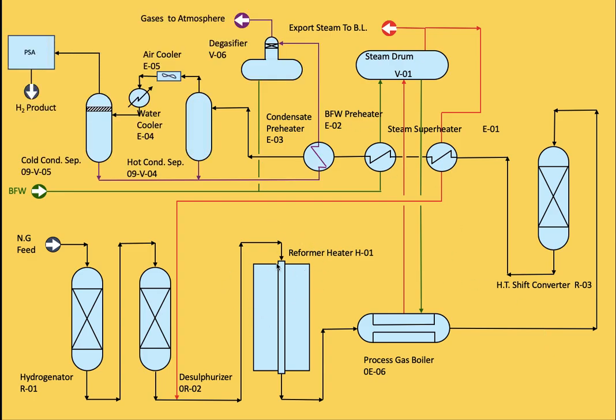So the main reactor here is the reformer, and we will see the shape of the reformer in detail. Then heat recovery and the shift converter, the high temperature shift converter. This catalyst has three types: FeO, which is iron oxide, Fe3O4, and chromium oxide, and some copper oxides to stabilize and promote the reaction at lower concentration of H2O.